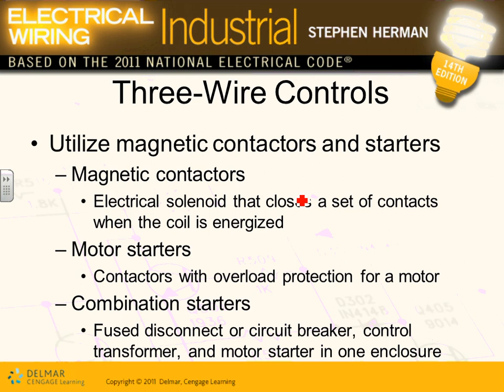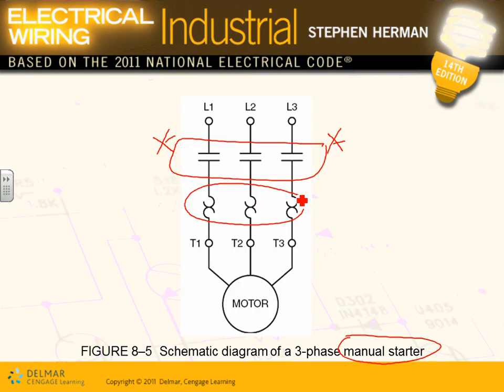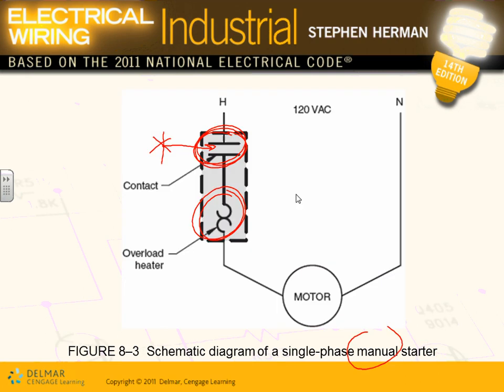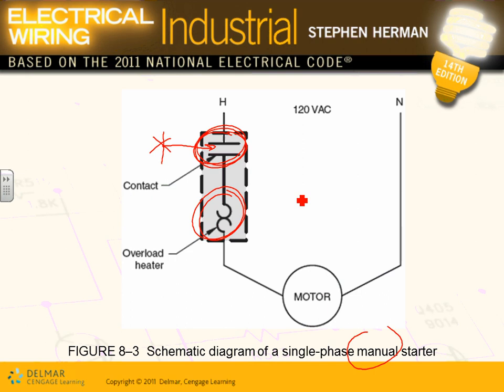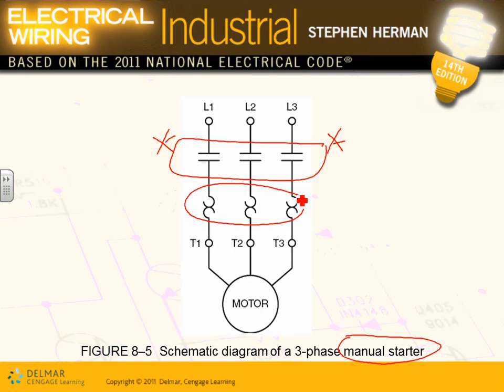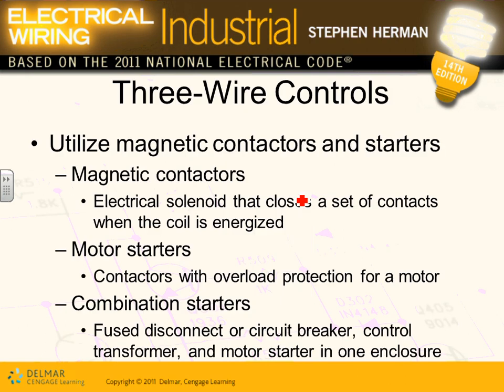So that's what they call two-wire control. Basically, two-wire control, guys, requires manual intervention if it's manual. If it's auto, like your thermostat, it will turn it on and off whenever it's needed, without intervention. So there's manual and there's auto.